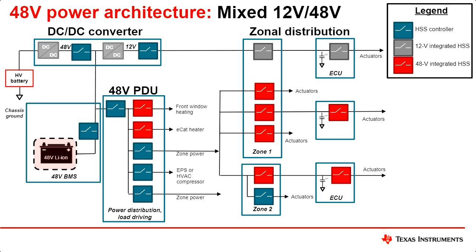The load current can be very high, and it can range from 50 to even 500 amps. And that's where there is a need for controllers which can drive external FETs, because after a certain level of current, it becomes really challenging to integrate the FET inside the same chip and achieve the same power density.